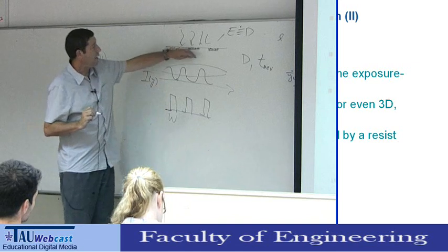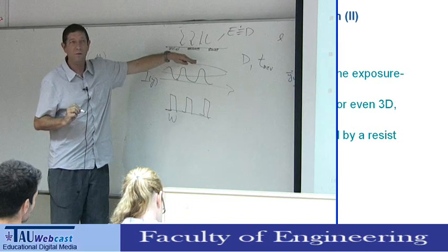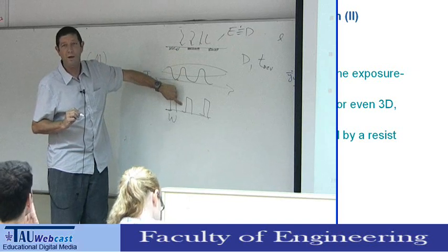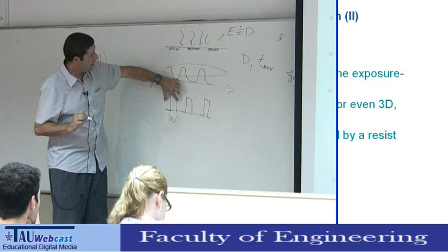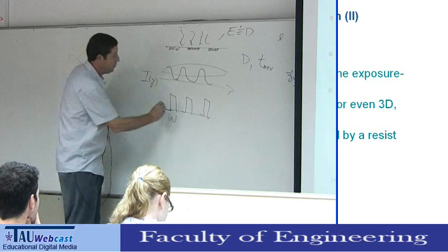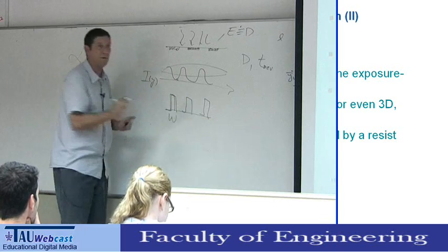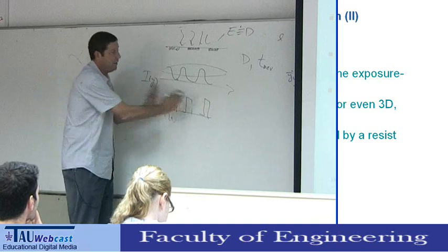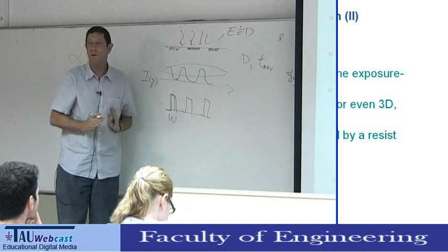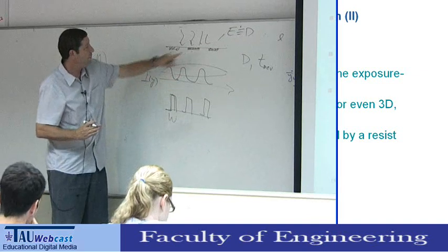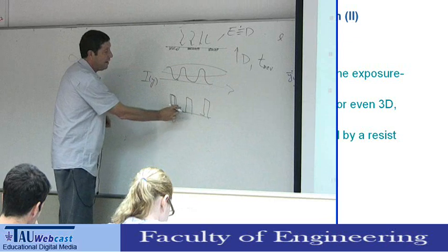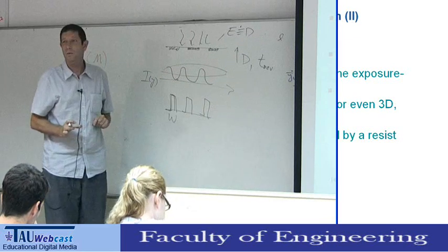Now let's say I increase the dose. More light will reach the wafer. The photoresist will shrink, because there's more diffraction, more light being diffracted to the side of the lines, and we get narrow lines. Also the same, if I increase D, I reduce the lines and increase the space between the lines.